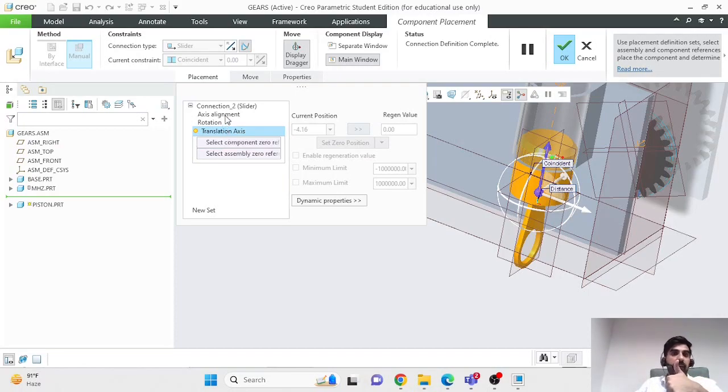The first thing that I defined was the axis along which my part will translate. Then I limited its rotation by giving it planes which need to be kept parallel, or if you selected different planes, they might have had to be kept perpendicular or at a certain angle, but what that does is that it stops your part from rotating.